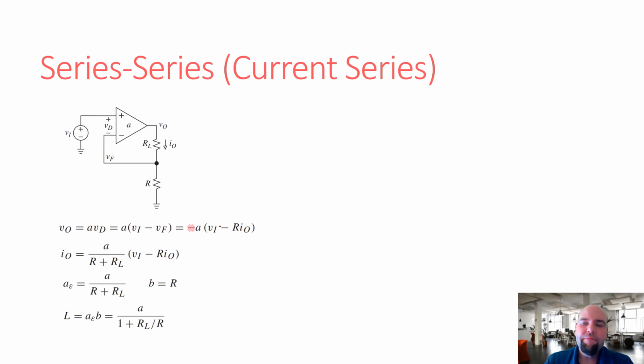What does that mean? Well, if you're ever measuring current in the lab, what do you have to do? You have to break the circuit, insert the current meter in series with your circuit to measure current. That's what we're doing. We're measuring current here. So what does that mean? That means, in this case, we have a load resistor. We have some current flowing through it. We are measuring the current flowing through that load resistor. Okay, let's see what that means. So let's analyze this circuit.